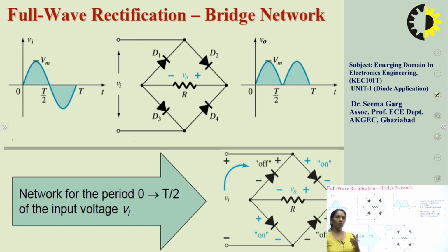So this is one advantage of the bridge rectifier over the center tapped full wave rectifier, because the fabrication of the center tapped transformer is difficult. Because the center of the secondary winding is being tapped, the number of windings across the first half and second half should be exactly equal to have an accurate result. And because of this, the cost of the transformer is also high.